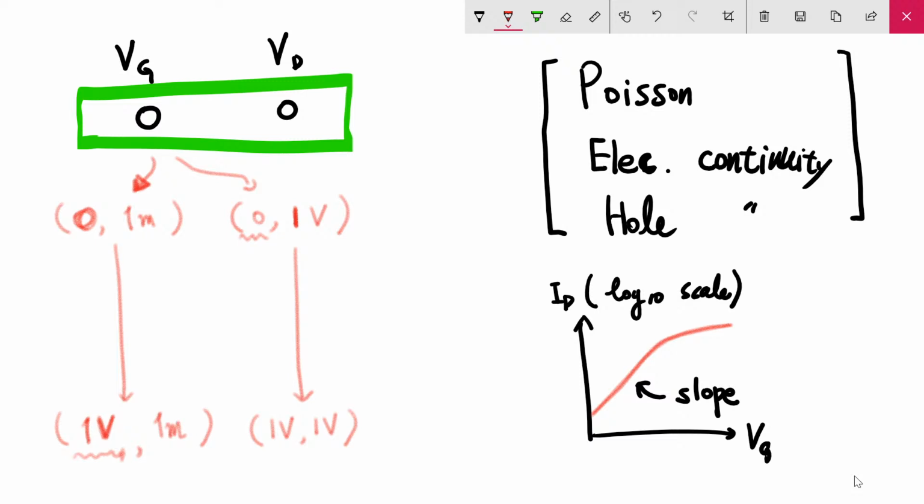Here 1 volt is not a fixed value, but just a representative value for the so-called VDD, the operation voltage. Nowadays this voltage is not exactly 1 volt, but slightly lower, about 0.7 volt, or even these days 0.6 or something like that. But as this is just a simulation, you can apply any voltage. So please increase up to the 1,1 configuration. Then now you will have this form.